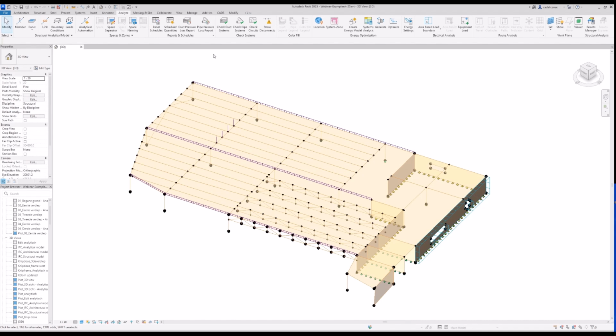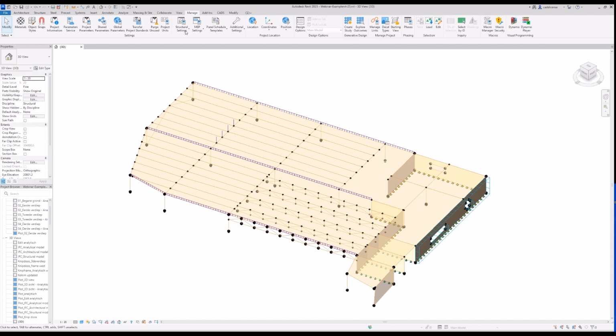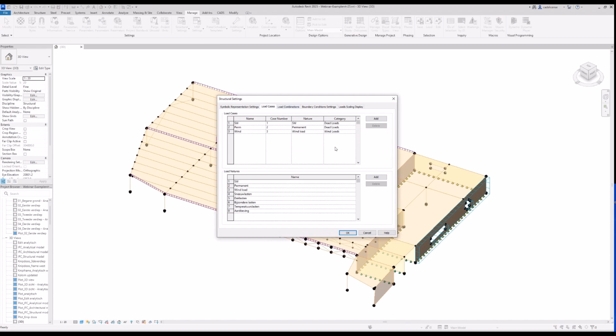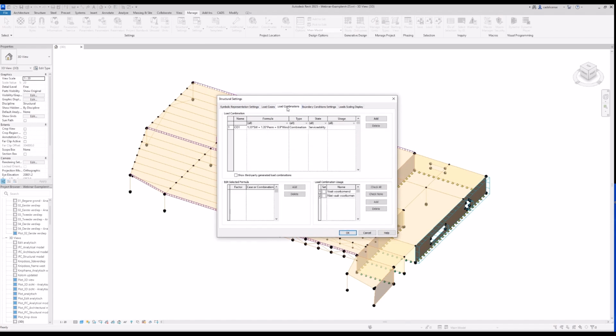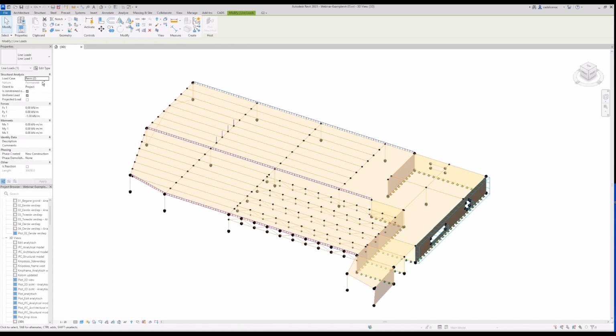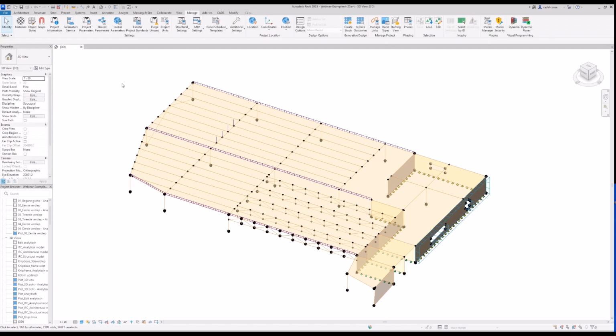In this analytical model, you can also define some load cases, combinations, and some loads. You can find the load cases and combinations in the Manage tab, and there you see that 3 load cases are created and 1 combination is created with these specific factors. These can be taken into account in SCIA Engineer later on if you'd like. We have added some line loads to the permanent load case, some nodal loads as well, and to the wind load cases we added an area load. So this is just to give you an overview of all the elements you can find in this project.